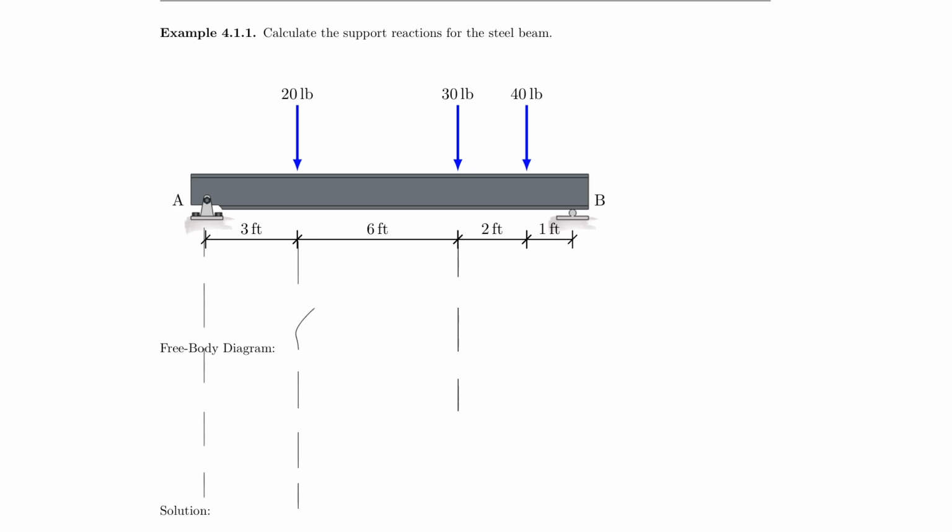And here we go. My next force and the end of the beam. And then I have to draw my free body diagram. And remember what we talked about, that the free body diagram is now representing a rigid body, and a rigid body always has a dashed line to identify it. You will learn more about this later, but for now, just apply a dashed line on the bottom. Sometimes you can put it on the top later on, but for now, just put it on the bottom.